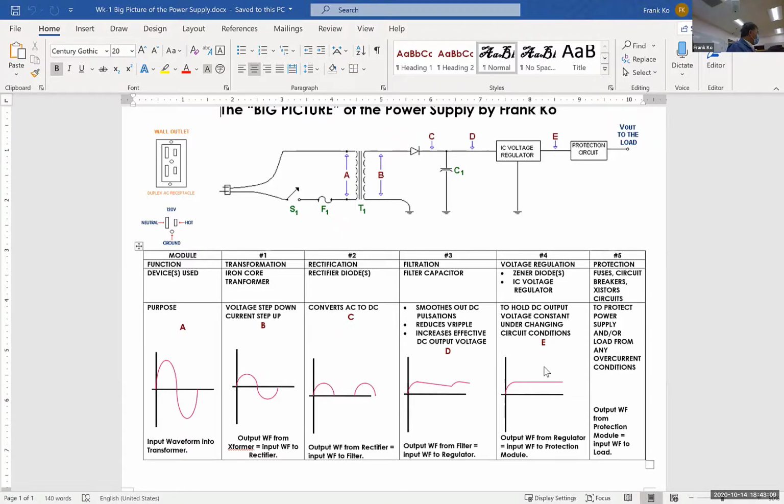For those of you who were with me for ESYS 50, I had assigned the students to purchase their circuit boards that had DC power supply on the circuit board, breadboard, yes? And what was different about that versus previous semesters where I had battery packs? The difference was with the battery pack, the batteries drain. They don't give you consistent voltage.